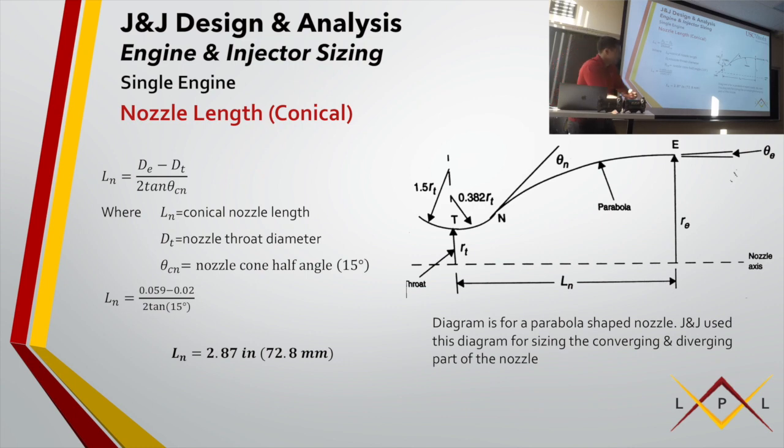As you can tell here, it's the diverging part. So it's right where the throat is, which isn't the end of the world. I think this range that they recommend is like 10 to 20 degrees or something like that. So you just pick the middle. And then these radii here, like I mentioned, are to figure out what shape this converging-diverging needed to be. You just plug in the radius of the throat to those there.